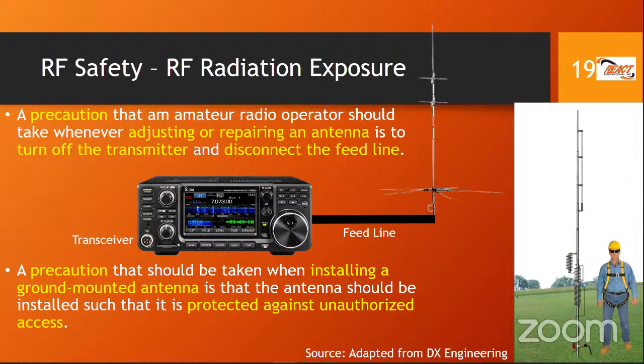do not leave it on, because next thing someone comes in the room and presses on the microphone or presses the transmit button on the radio, or a book falls on it inadvertently and it's transmitting and you are holding on to this antenna. Not good at all. So as a safety precaution, take it off.